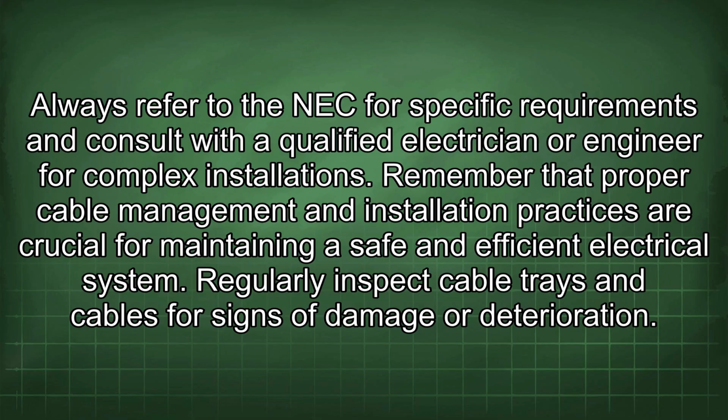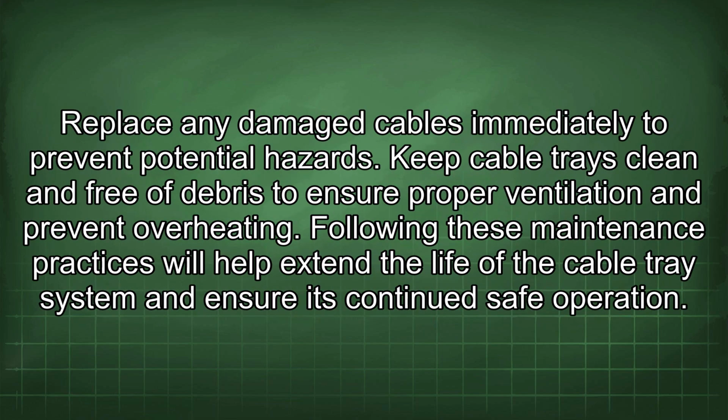Regularly inspect cable trays and cables for signs of damage or deterioration. Replace any damaged cables immediately to prevent potential hazards. Keep cable trays clean and free of debris to ensure proper ventilation and prevent overheating. Following these maintenance practices will help extend the life of the cable tray system and ensure its continued safe operation.